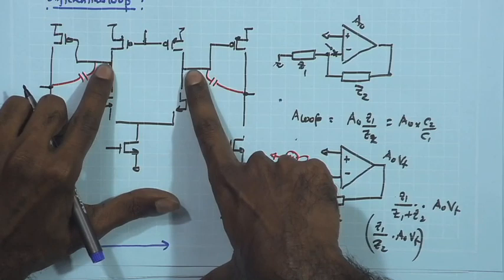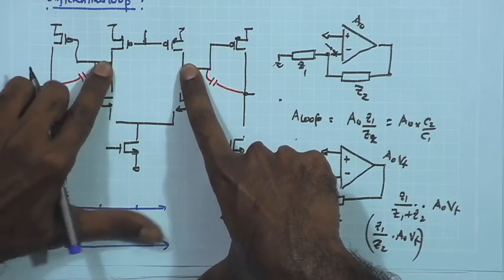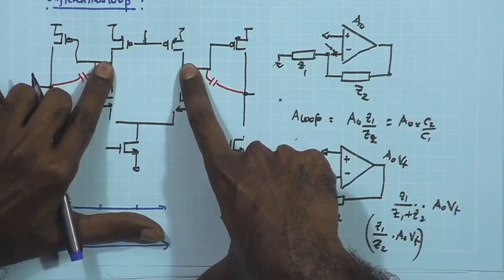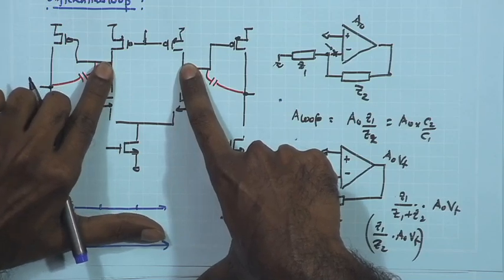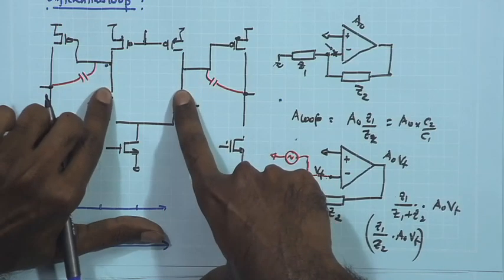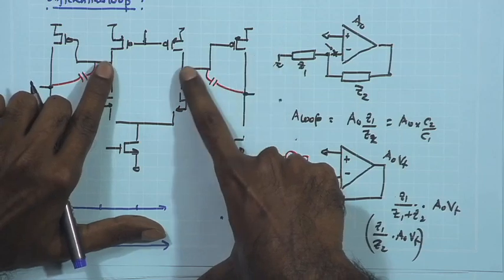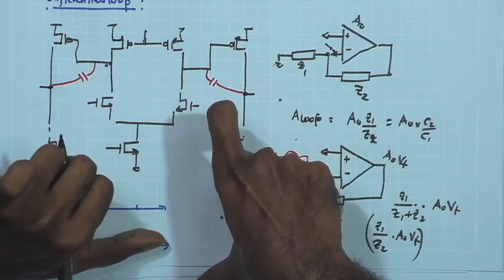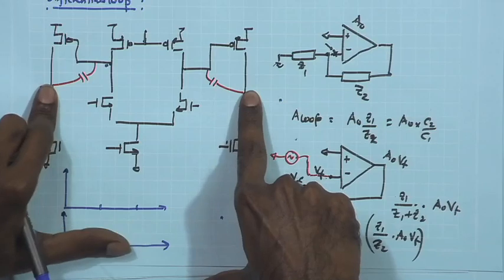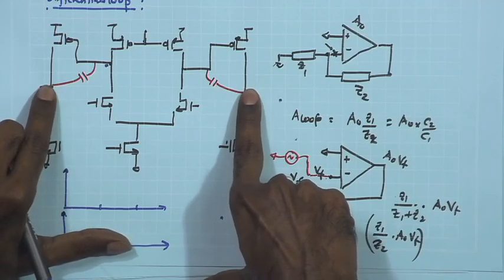the only thing is the impedance over here, if you are looking at the common mode analysis, rather than RO by 2 becoming RO, that is what we have discussed earlier, and we will go into that in a little more detail. We will look into the derivation of the impedances at the cascode node when we look at the cascode or folded cascode amplifiers. So, if you are not clear about that, you can wait for a while. And the final output stage is also having almost the same small signal resistance and capacitance.